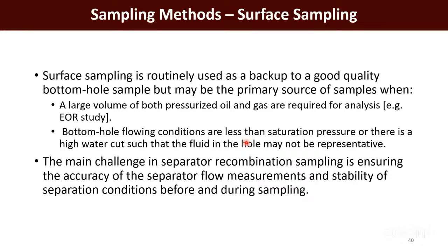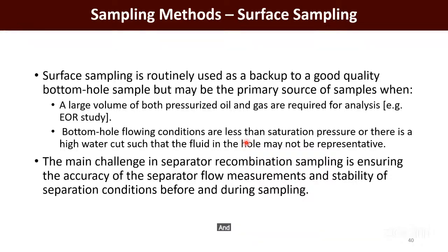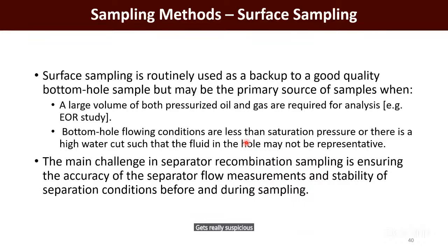Like I mentioned, the main challenge of the recombination is the accuracy of the separator flow measurements and the stability of the separation conditions before and during sampling. It should be stable, and we should have a clear trend of the gas oil ratio especially, and the water cut.